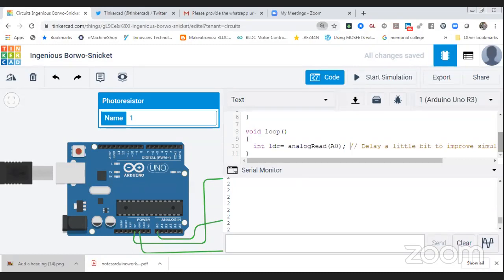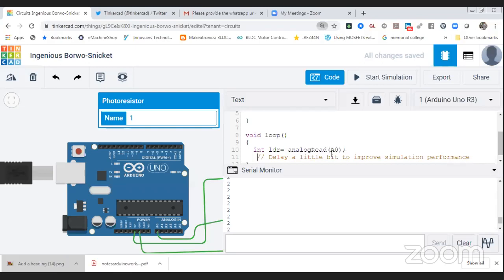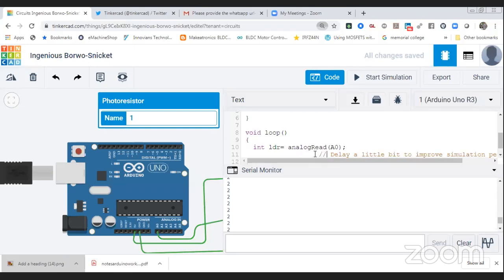The first line we have defined over here, this analog input. This one is for Serial.print, and then this line. Now if you want to print this value at serial, this one, double slash, is for a comment. This line will not be executed in the program. So if we want to print serially, we have to write Serial.print, and then we have to put that LDR value, that variable in which our analog value is being stored. Yes, my code is complete.